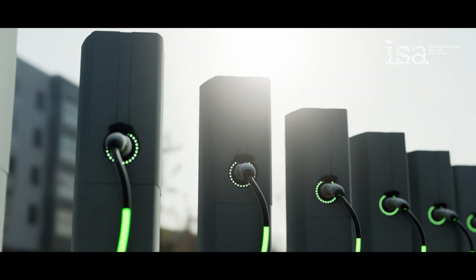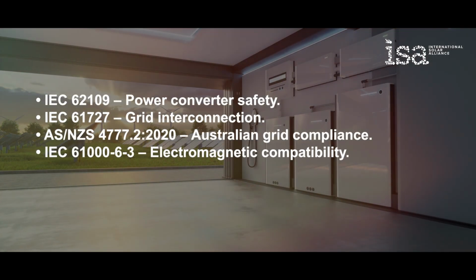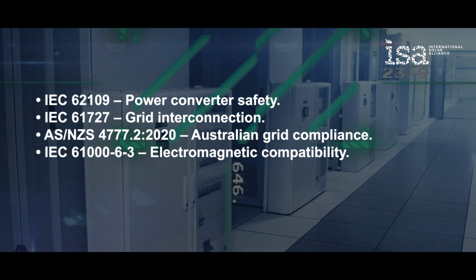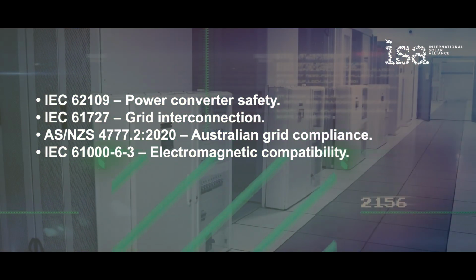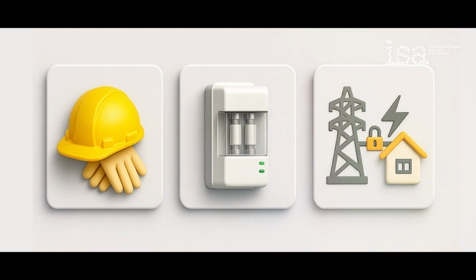Inverter safety is paramount to ensure user and grid protection. Major standards include IEC 62109 Power Converter Safety, IEC 61727 Grid Interconnection, AS/NZS 4777.2:2020 Australian Grid Compliance, and IEC 61000-6-3 Electromagnetic Compatibility. Key safety functions: anti-islanding protection, surge protection, DC/AC Type 2 SPDs, overvoltage, short circuit, and leakage current detection, ground fault, and grid monitoring systems.